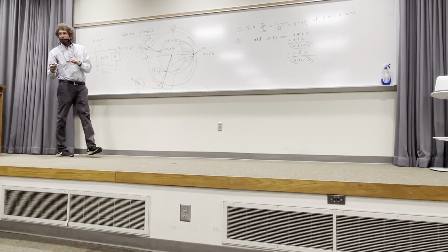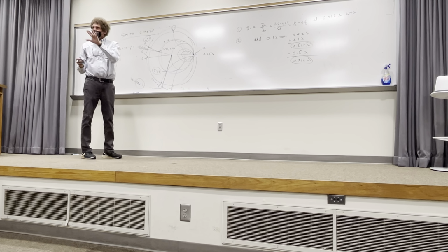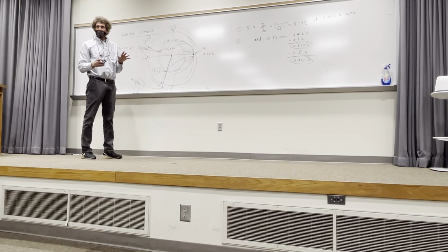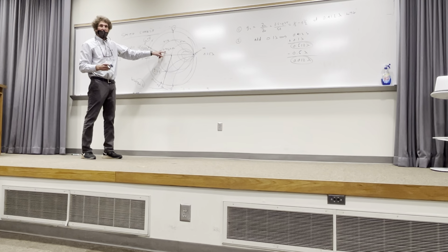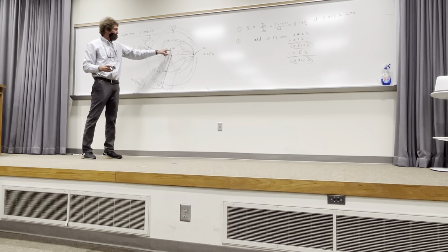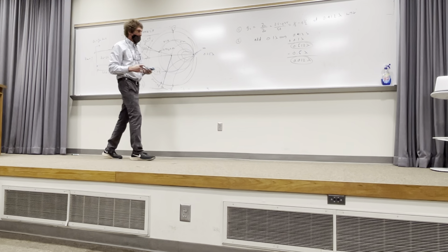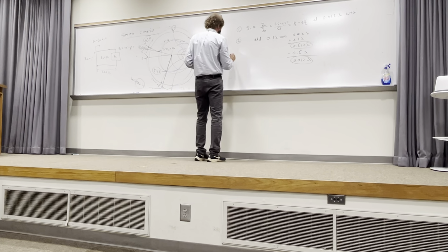So, would you do me a favor? The normalized value that we used was 50 ohms, wasn't it, class? Yes, sir. Take 50 ohms and multiply it by 0.4, and then tell me what you get, and then take 50 ohms and multiply it by 0.06. And that will be Zn.